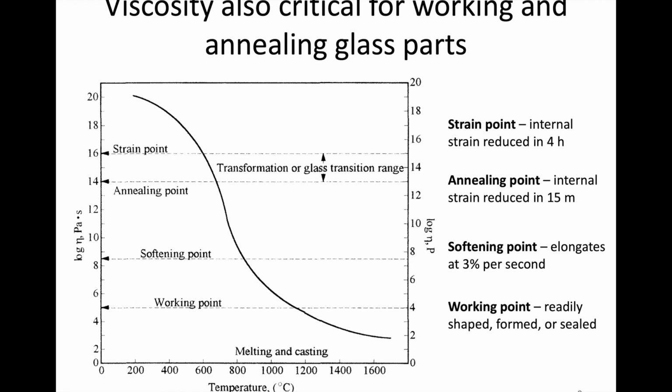The nitrates in the ion exchange bath only melt at a certain point, and then at a certain point they become unusable, right? So you want to look at the upper temperature of those nitrates to see what limits us from going up and up in temperature.